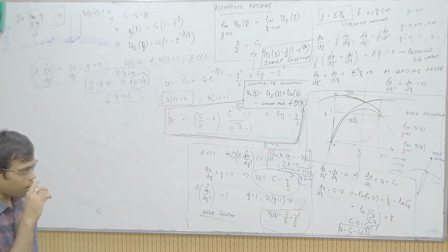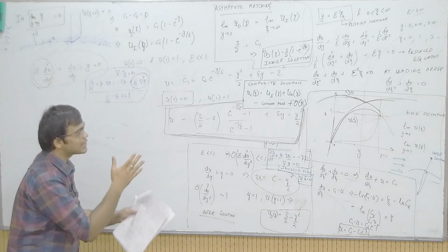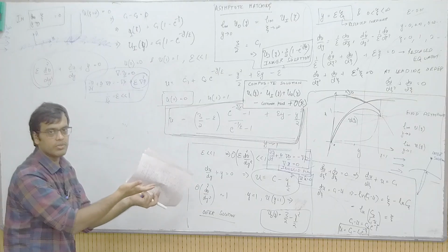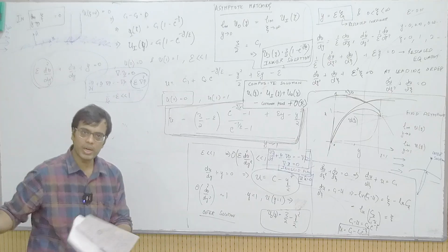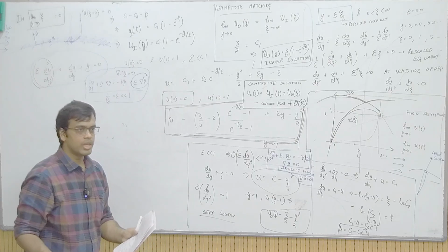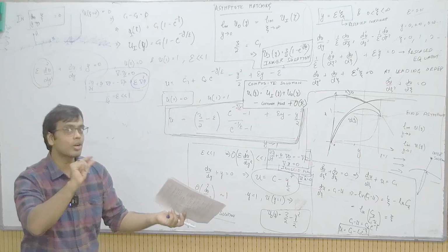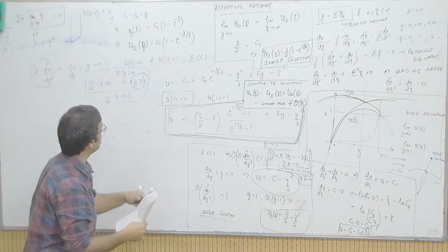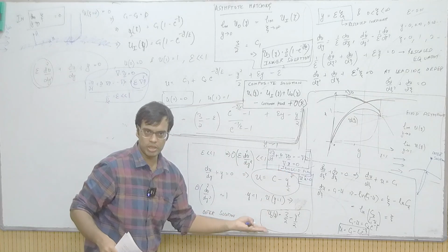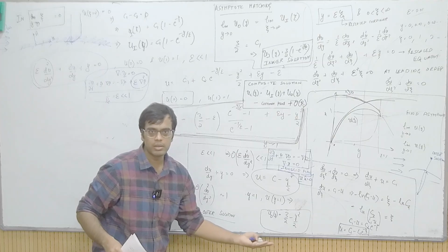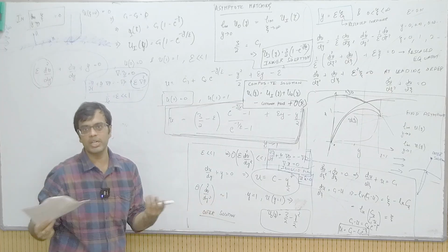So that's a very wrong line of reasoning, because the distinction between boundary layer and an inviscid flow appears due to the high Reynolds number flow regime. In the low Reynolds number flow, there is no requirement of making this distinction. You shouldn't say we did not account for a boundary layer. The reason why we need a boundary layer in high Reynolds number flows is because the outer solution is not able to satisfy the no slip boundary condition. In low Reynolds number flows, we did not have this problem where outer solution and inner solution were different.